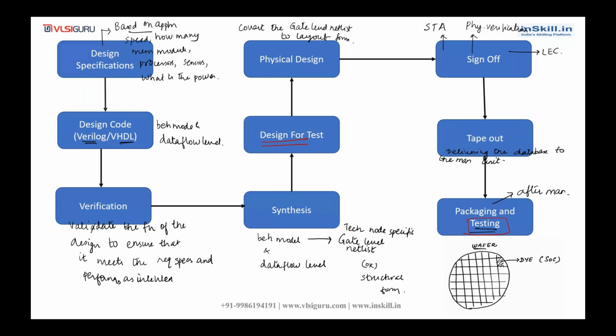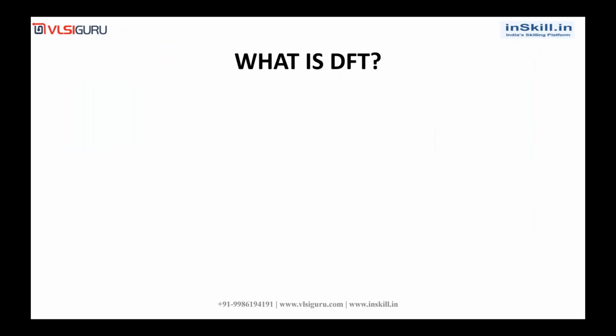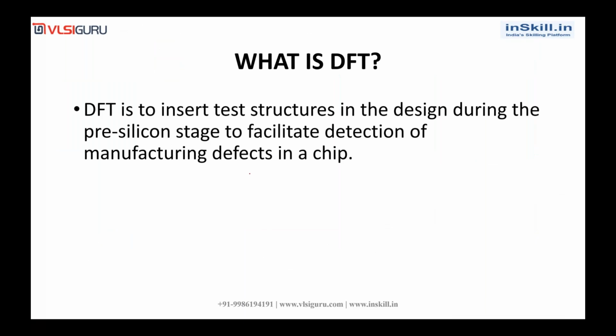So what is DFT? DFT means inserting test structures in the design during the pre-silicon stage. Pre-silicon stage means before manufacturing. This is to facilitate the detection of manufacturing defects in the chip. To facilitate means to help in the detection of manufacturing defects in the chip.